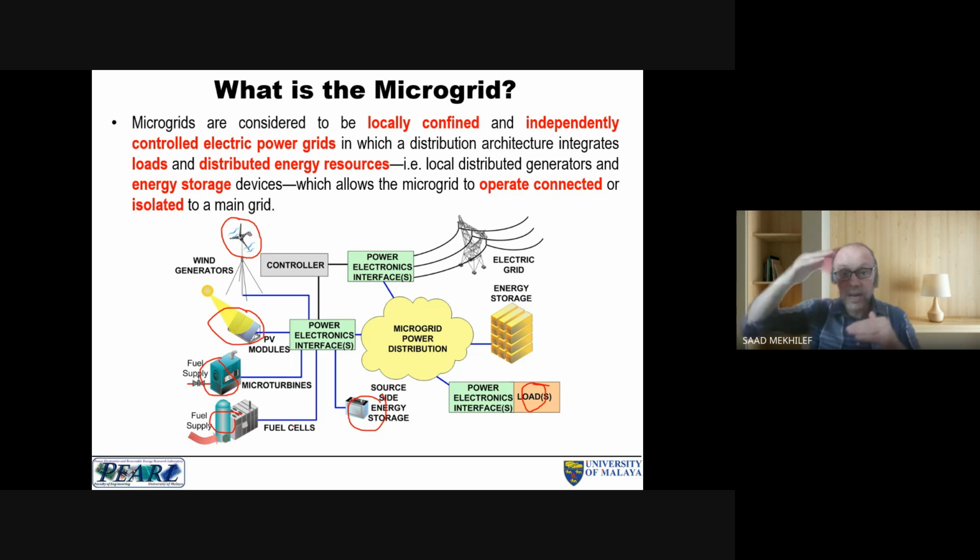This is very important. For example, if I want to install a solar power plant, solar photovoltaics, what is the solar access? How many kilowatt hours per square meter? What are the directions? What is the best tilt angle? This I would call site assessment and technical assessment, which gives you an idea of what will be the optimum design, because we cannot over-design. We cannot also under-design. So it should be optimum.